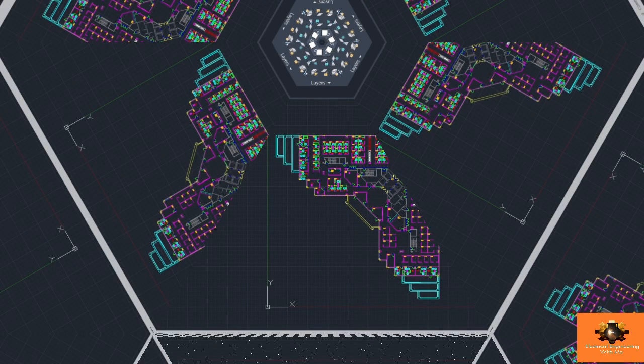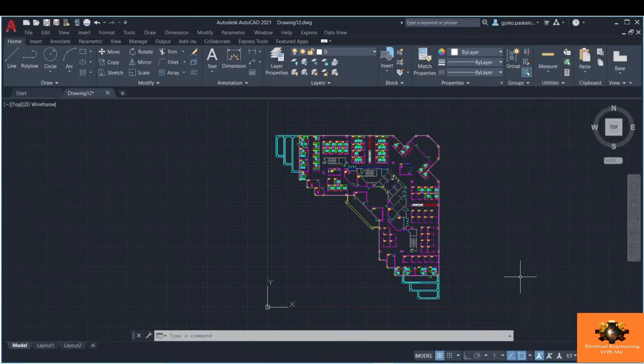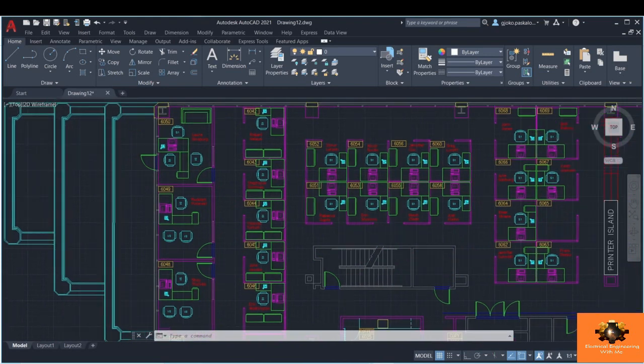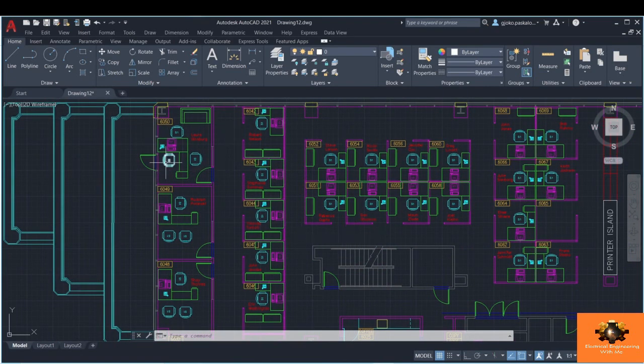Okay guys, in this lecture I'm going to show you how to deal with attributes, how to modify them and visually inspect them. And for that I've inserted this drawing here, and if I zoom in you can see that all the text input actually is attributed text defined into a block. And if I want to deal with attributes, I will go in this section here, and the modified tool is this, so I'm able to select a single attribute, and let me select one just to see.